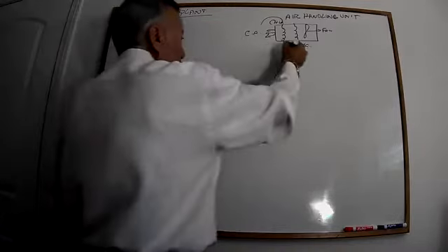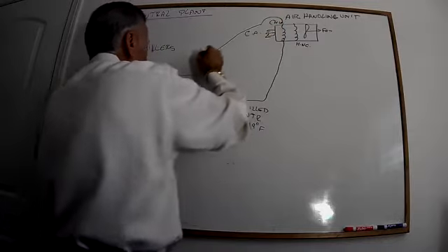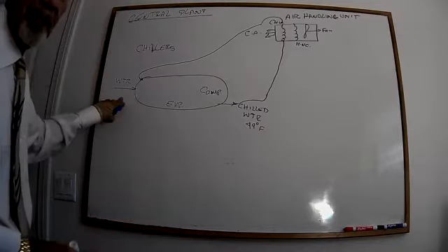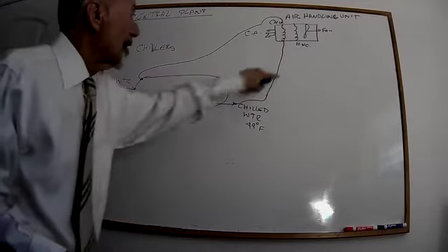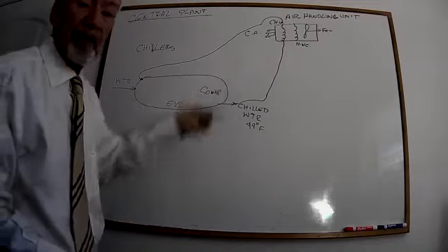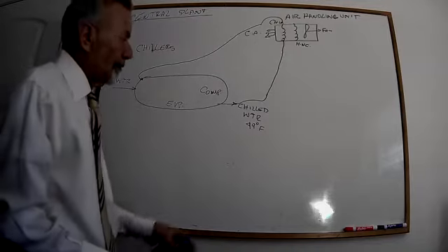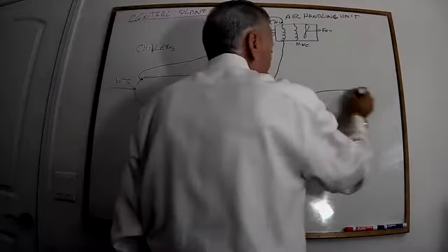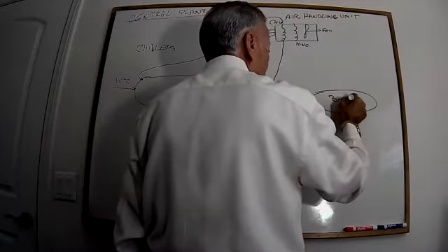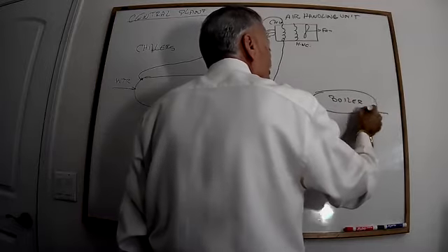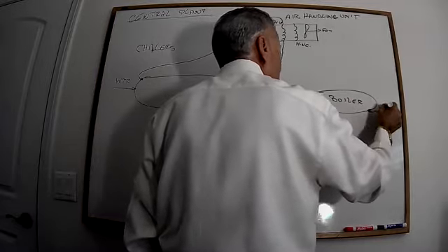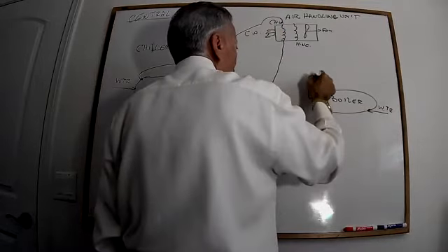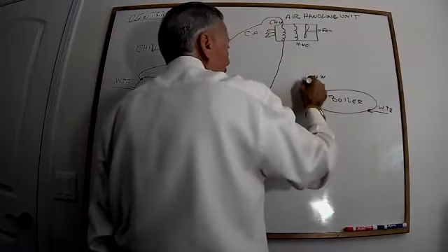Now, this chilled water goes here and then comes back to the chiller again. We cut off this water from outside, so we create a loop that just keeps going back and forth. From the hot water side, there is a boiler that the water goes in, and then you have hot water coming out.